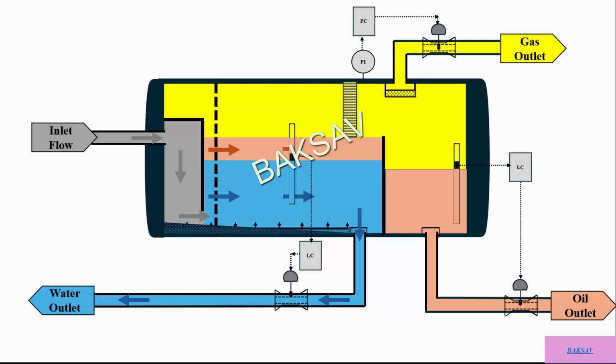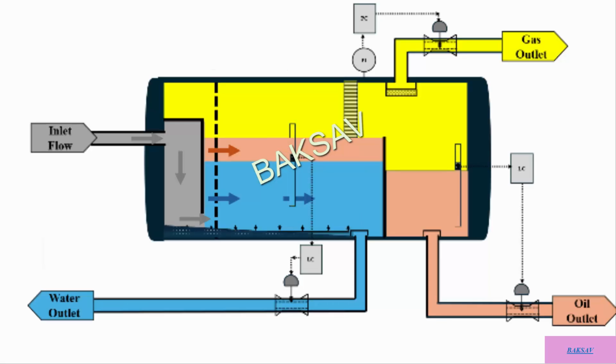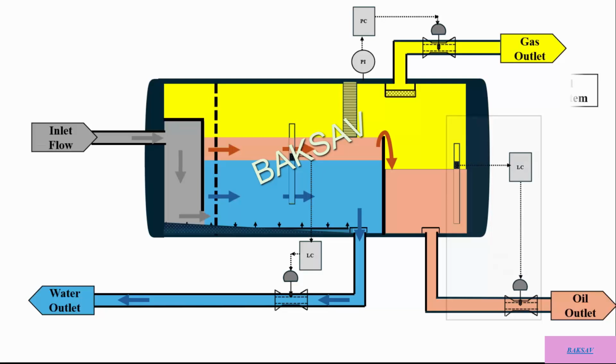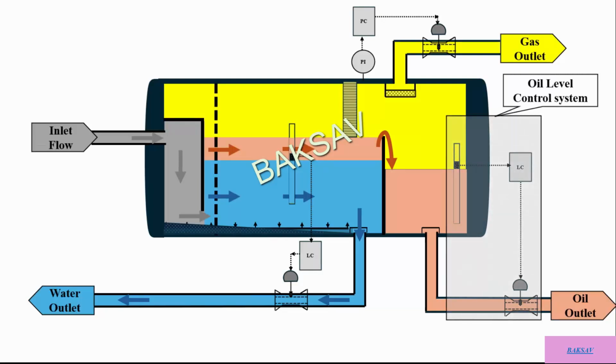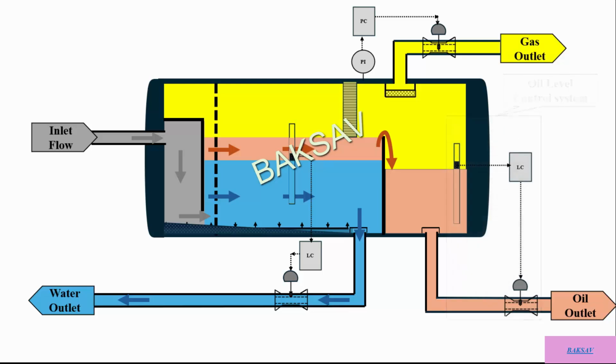Separated oil is accumulated at the middle level of the separator's main section and flows by skimming over a weir plate to the oil section of the vessel. As the separation process continues, additional oil volume enters the vessel and the separated oil level rises. Excess oil volume leaves the separator under control of the separator's oil level control system as described previously. A vortex breaker system on the vessel's oil outlet prevents the vortex effect that can be caused by gas entering the oil outlet line.